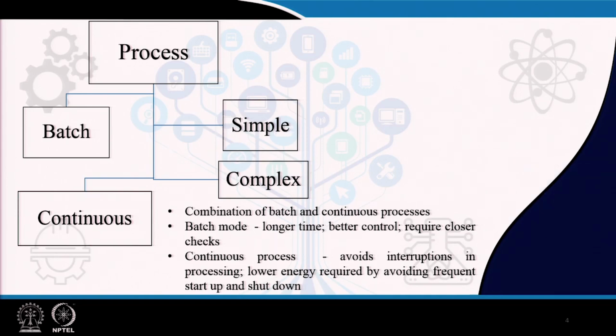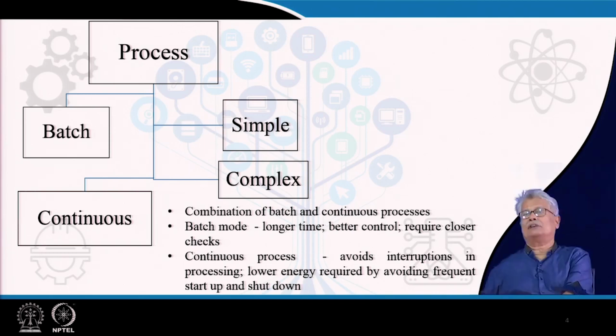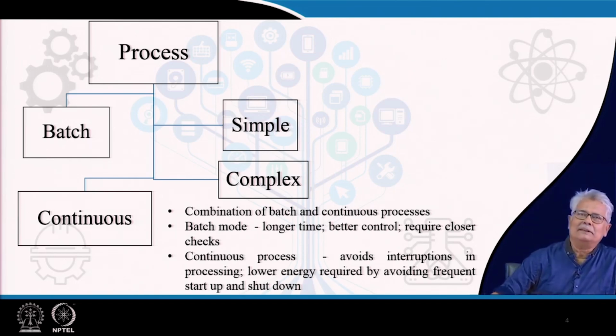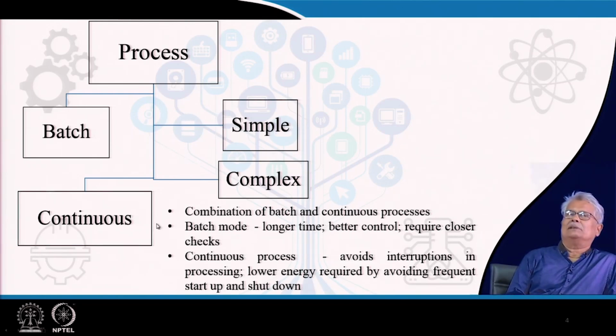In case of a continuous plant, definitely we would like to monitor the temperature and pressure or other process conditions, but at the same time I'd like to say here that in case of continuous processing, the material that I produce right now goes to the storage and mixes normally with the rest of the material. So there is a chance that if I am sending it to a particular tank, possibly my entire tank will be going off if I have something wrong in my continuous processing. So these are basically the basic differences or merits and demerits of batch.